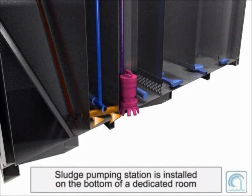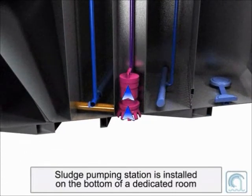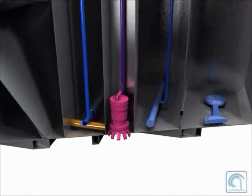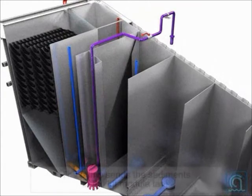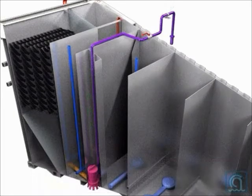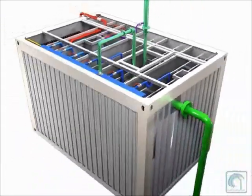The sludge transfer pipe passes through the pre-aeration chamber and leads to the pumping station, which is located in a dedicated compartment on the bottom of the first aeration chamber. The pump moves the solids back to the lift station. If necessary, the sludge can be sent to an optional dewatering process.